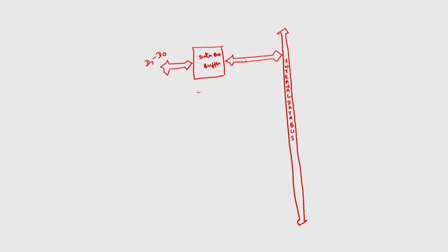Then we have read write control logic. This is also bidirectional. Some control signals are input signals, some are output signals, because it can read or write memory as well as IO. What are the different signals? The very first signal for any read write control will be chip select bar. You first have to select this chip using some address decoding logic.